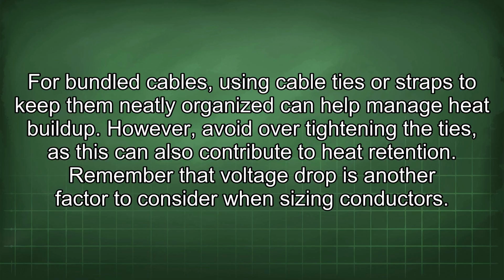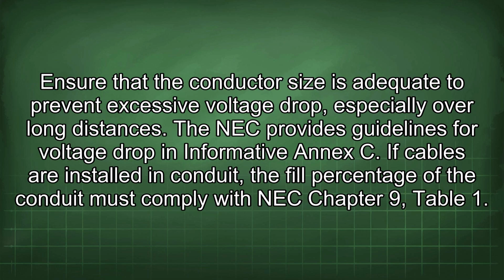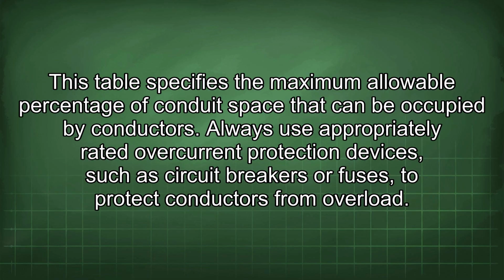Remember that voltage drop is another factor to consider when sizing conductors. Ensure that the conductor size is adequate to prevent excessive voltage drop, especially over long distances. The NEC provides guidelines for voltage drop in informative Annex C. If cables are installed in conduit, the fill percentage of the conduit must comply with NEC Chapter 9, Table 1. This table specifies the maximum allowable percentage of conduit space that can be occupied by conductors.